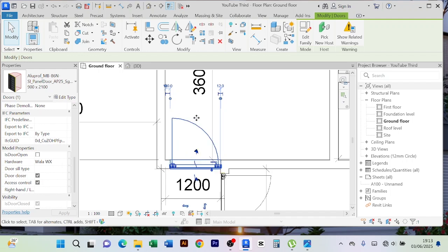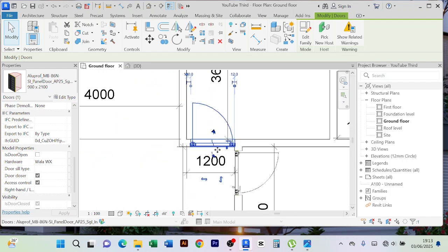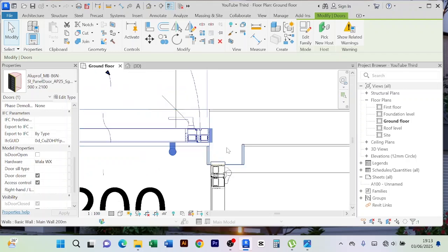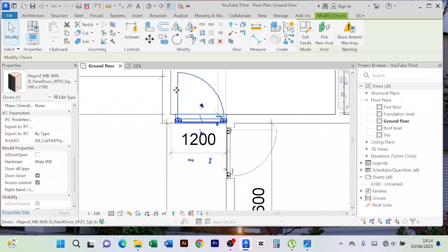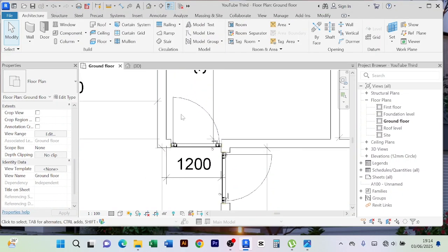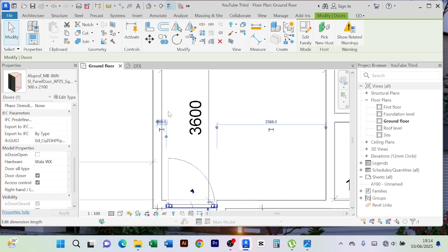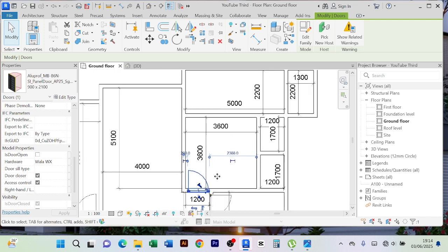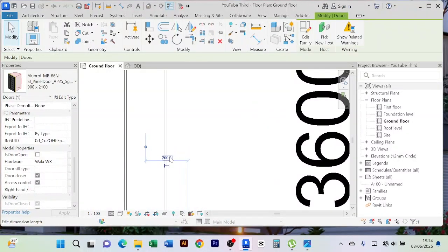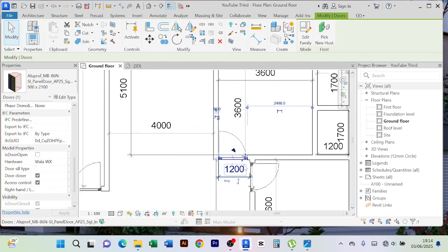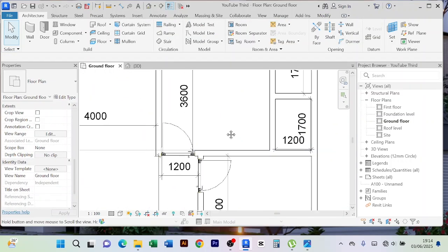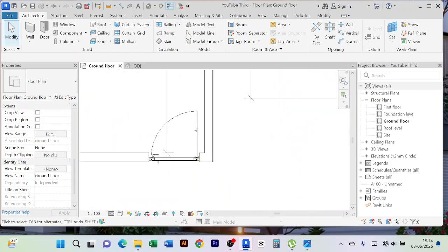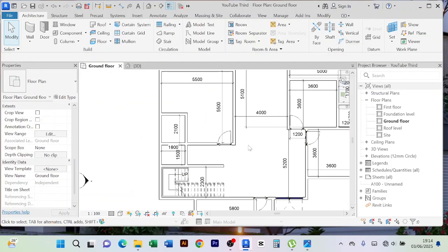What is it saying here? It is saying that this space is not enough. This door is entering inside the other wall. So we are going to reduce the 100 we gave to something else. Let's say, click on that, we say 90 and see if it will have anything better. I guess, yeah, this one is better now. It is not warning us anymore. And then of course this one I think is already perfect.